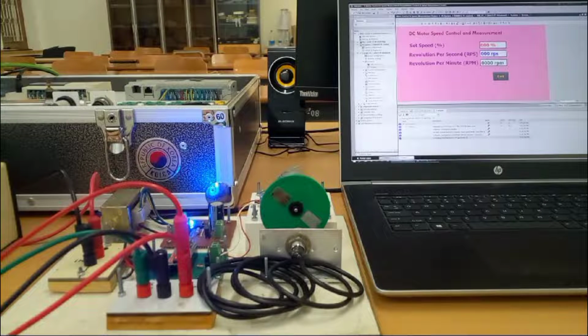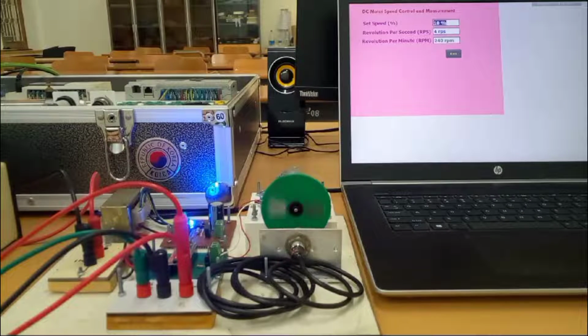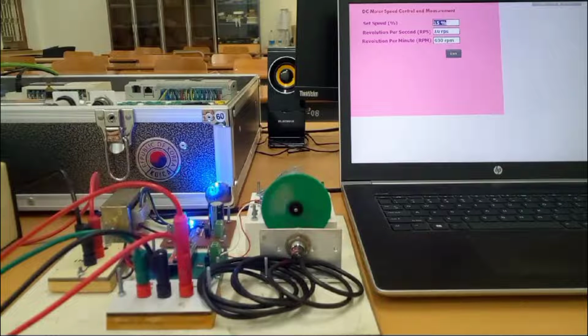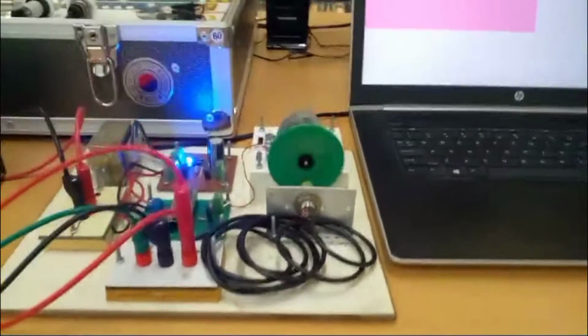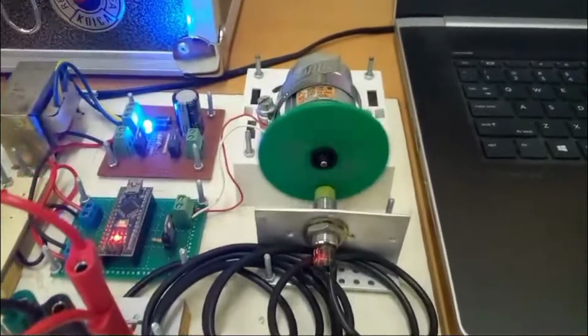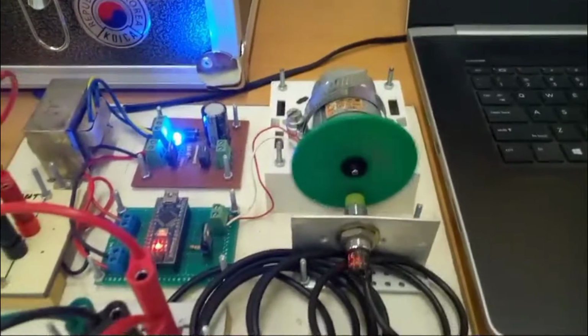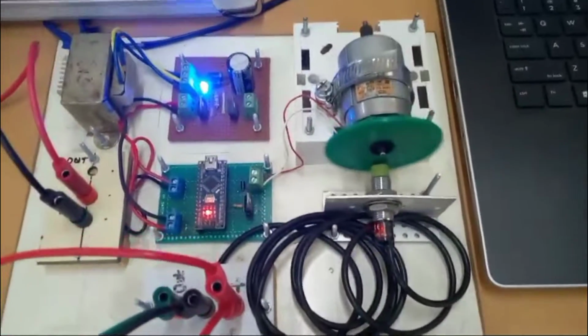Today I am going to show you the motor rotational speed measurement using PLC high speed counter and monitor this speed measurement from the TIA Portal SCADA screen. Here the proximity sensor is used for sensing the rotational speed of the motor. Through this video I will show you the hardware connection of the proximity sensor with the PLC digital input, hardware configuration of the PLC digital input as high speed counter, PLC ladder diagram for high speed counter, and finally control and monitor the speed of the motor from the SCADA screen.